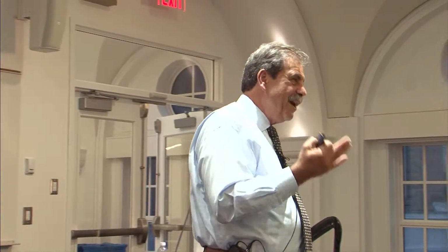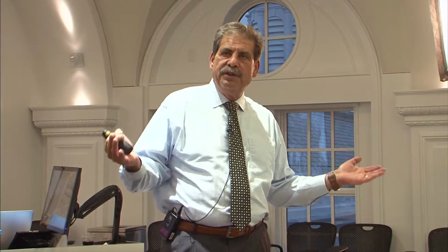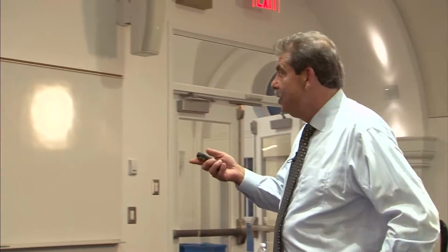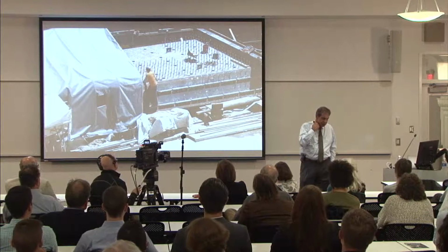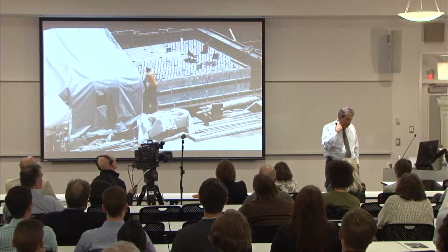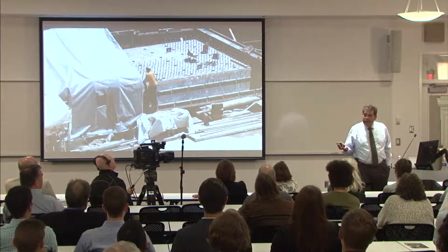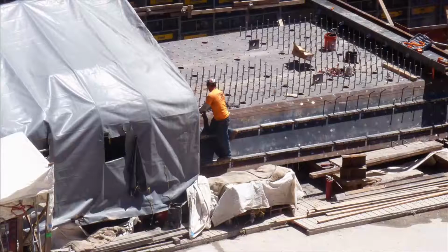So another challenge. The way we responded to a lot of the criteria was not to have exposed structure. And what I mean by that is we removed potentials for failure and targets of opportunity by eliminating them from the design. So we took our columns and we hid them. When we didn't hide them, we made them incredibly robust. What you see here is a column lying on its side, one of the 4 that support that bridge I just showed you, that was so large and massive that it couldn't be built off-site. It came to the site in 6 or 8 major pieces.